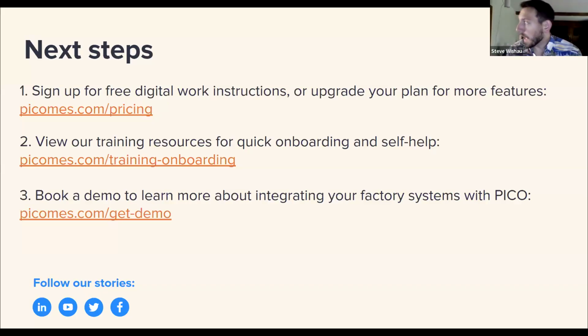To use my battery example, how many times has my robot faulted and dropped a battery that was being loaded into my individual modules? Depending on how that machine is set up, we can receive those paths or faults through that same type of communication that we use for standard operating behavior. So for tracking that, whether it's a version of first pass yield or how your equipment's running, we want to make sure we're capturing and registering that information as necessary as well.